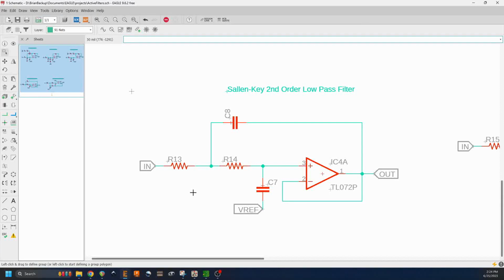And in fact, in the pro audio world, doing fourth order filters, which roll off at 24 dB per octave, is really common in high-end systems. So, you can cascade these and build them up to be even more order. But, if we have 4 passive components and our op amp here, what would be the advantage then of setting it up this way versus setting it up as just 2 cascaded RC low pass filters?